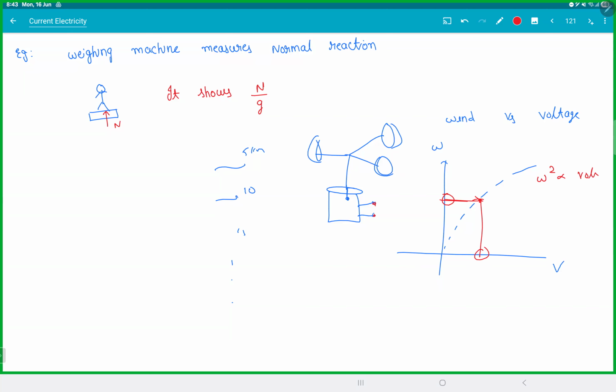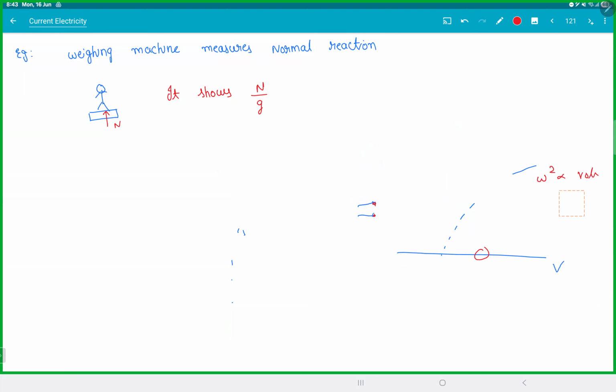So we have manipulated, so from the voltage you're trying to find the wind speed in reverse now. It is not a great design, but we write something. Something similar we are doing here. What we are doing here is manipulating this galvanometer to show you the capital I. So the capital I is Ig times (1 + Rg/R shunt).